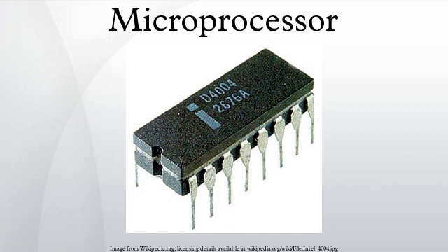Instead of processing all of a long word on one integrated circuit, multiple circuits in parallel processed subsets of each data word. While this required extra logic to handle, for example, carry and overflow within each slice, the result was a system that could handle, say, 32-bit words using integrated circuits with a capacity for only 4 bits each.